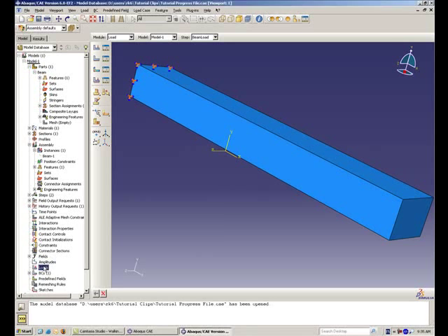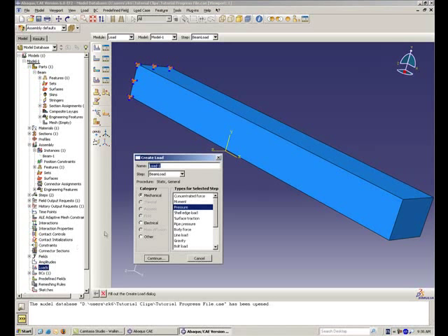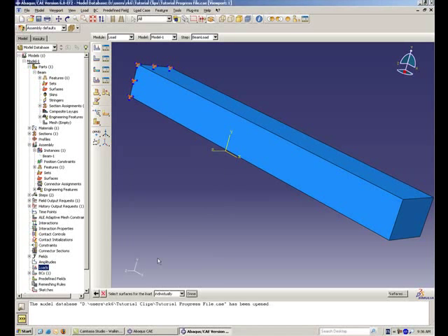Now you can apply the load on top of the beam. Double-click Loads in the model tree and name the new load Pressure. Select Beam Load as the step in which the load is applied. Accept Mechanical in the category list, and choose Pressure in the Types for Selected step list. In the viewport, select the top of the beam as the surface where the load will be applied.